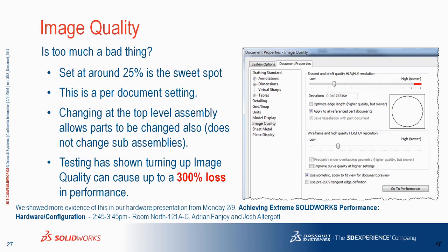In some environments, we have folks that make very large assemblies, like a die assembly, a progressive die, comes to mind. If they make very, very small parts with a progressive die, you can have that phenomenon happen. When you zoom in on the small parts, they'll be all jagged or hexagons instead of round, and you need that image quality set higher. The key, though, is to set the image quality higher for the individual part and not for the assembly or the rest of the model.